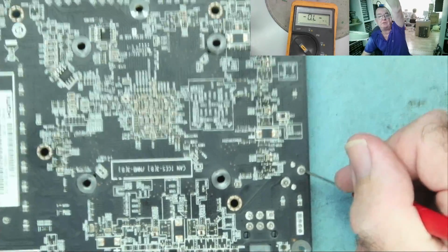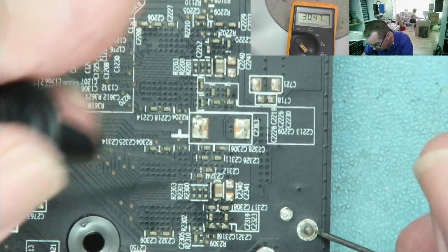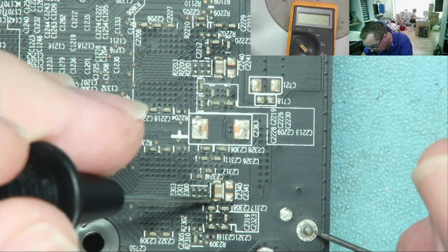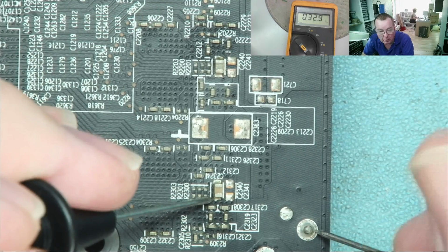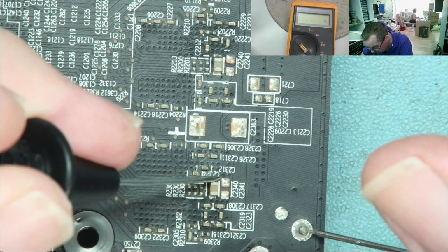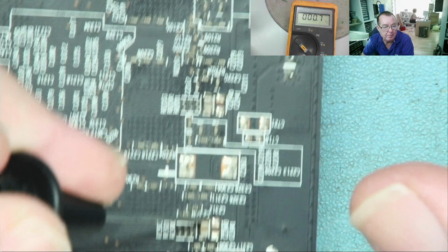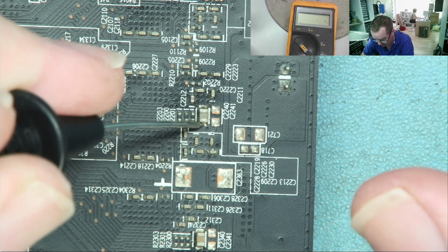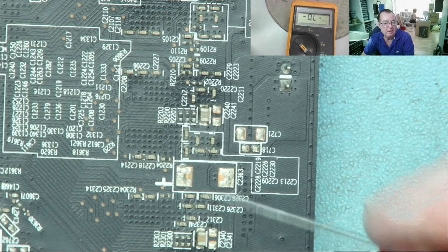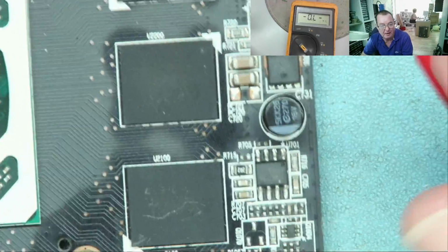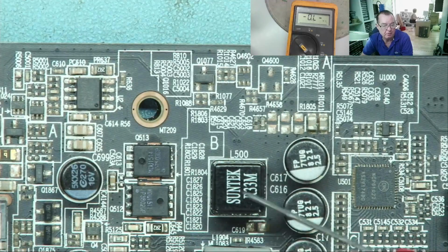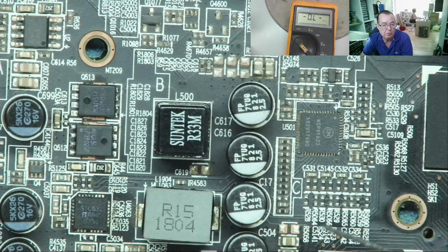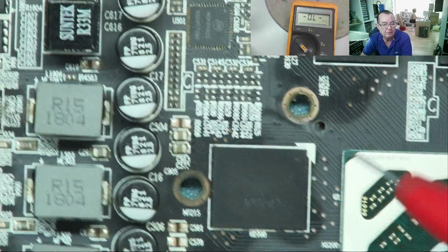Let's look for some capacitors. Okay, that's some capacitors here. So from the supply rail, yeah, look, it goes to these capacitors here under the RAM. Yeah, 33. So we can say pretty confidently that is the RAM supply. And this one is the memory controller. And again, that one only really supplies the GPU.